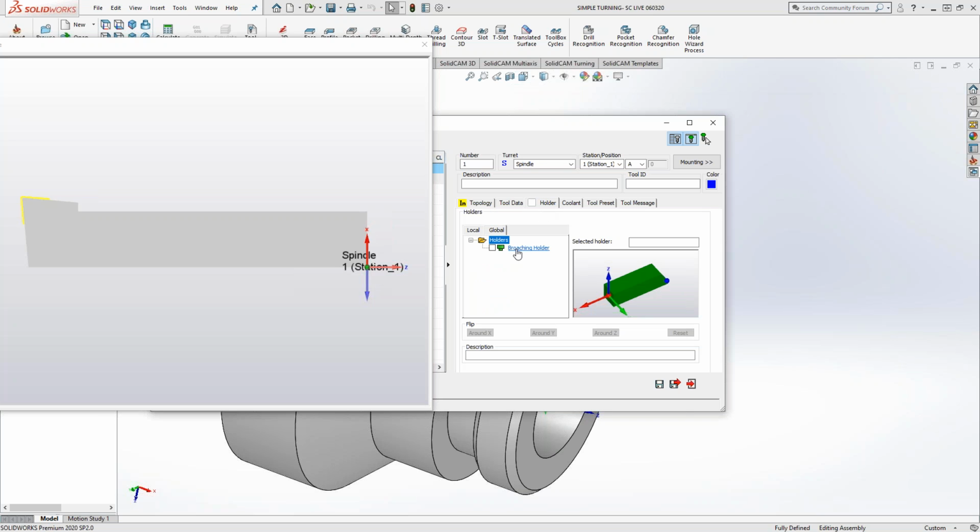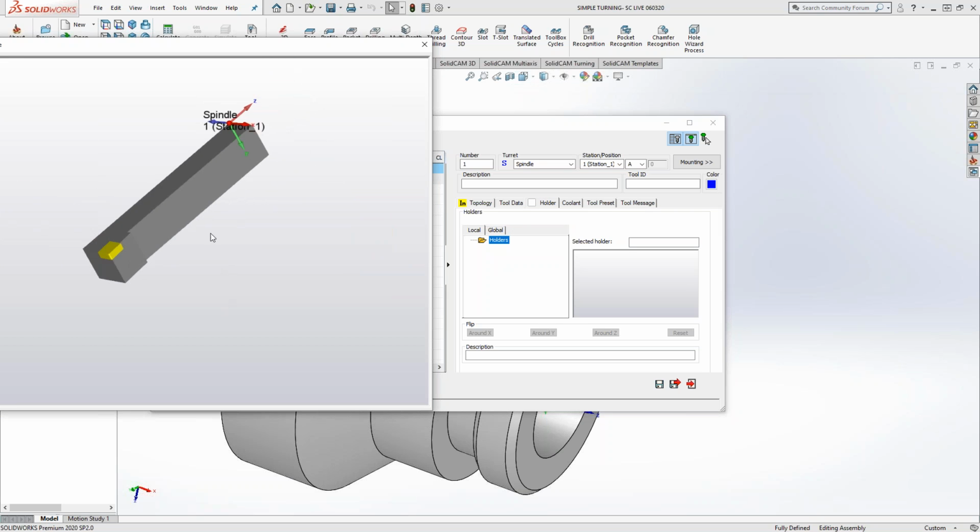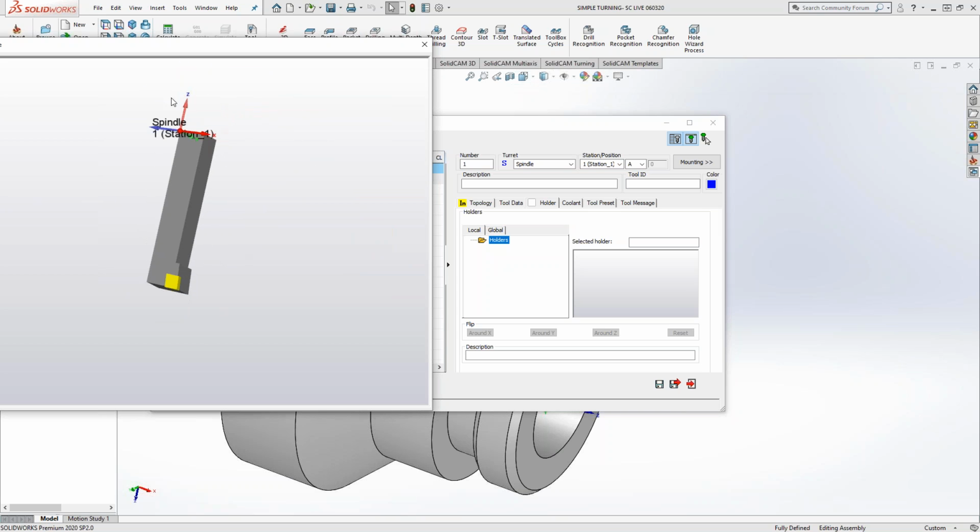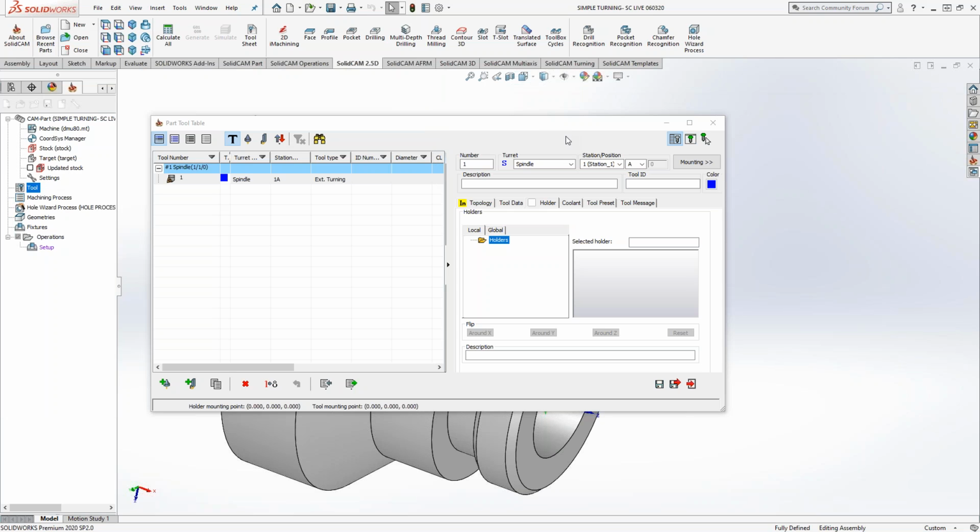Holder, same thing as before. Actually in this case, your holder is a little more related to the fact that you're going to have a special holder to hold this in your turret. So this is where your STL creation skills will come in, because you're going to use the STL format to create your holders. Or if you're just bringing in a holder to hold the insert, it's still defined the exact same way. For that, you can see our tips and tricks video on our YouTube channel. Or if anyone has a unique holder they've been having trouble with, later on in today's class, we're going to give you my email. You can send me your part if you want to see how we can define that for use in turning.